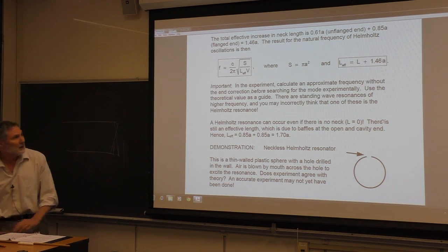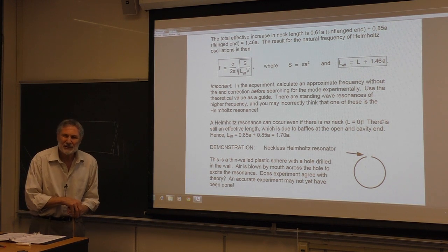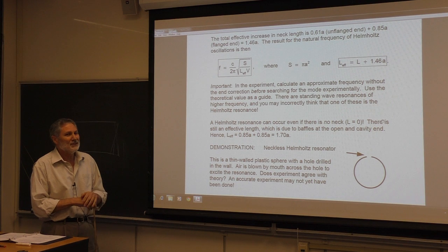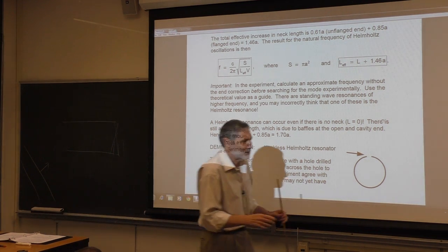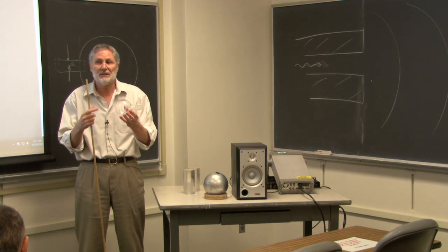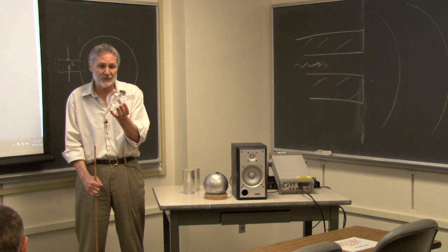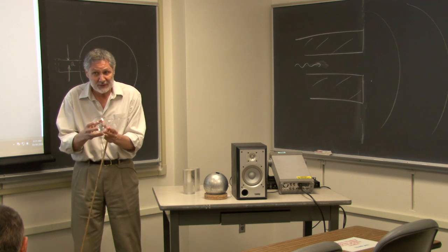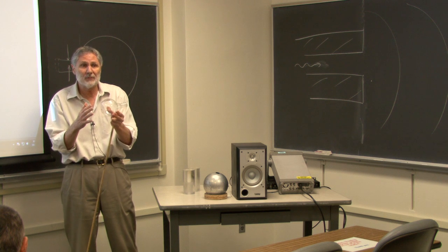Okay, so here's something important. The distance learning students, I guess, don't have to worry about this. But 1 year that we did this, we had a bad experience. The students in the lab: the Helmholtz resonance will give you the lowest acoustic frequency you can have in here, right? But if you're sweeping for it, you could miss it and go to a higher frequency, one of the pipe type modes, much higher frequency.